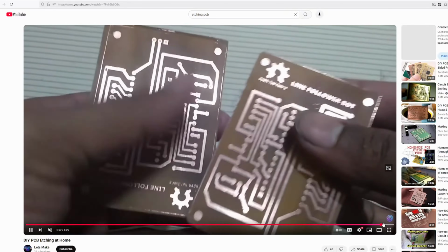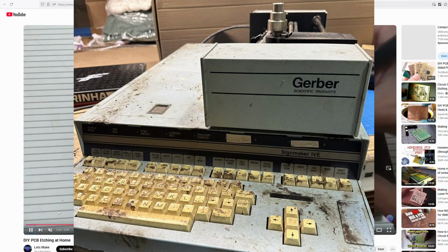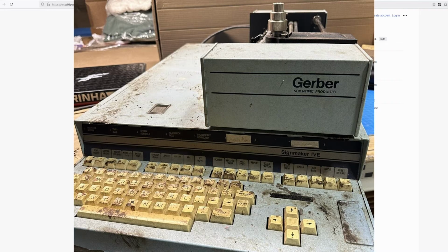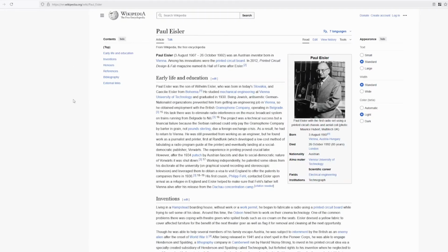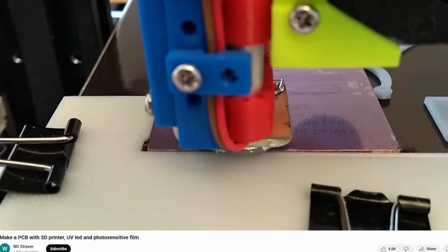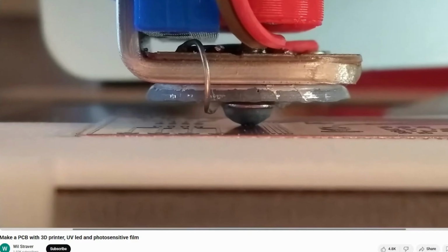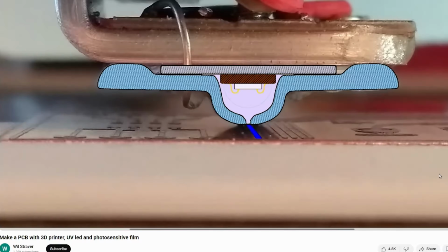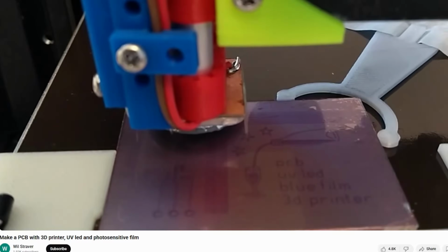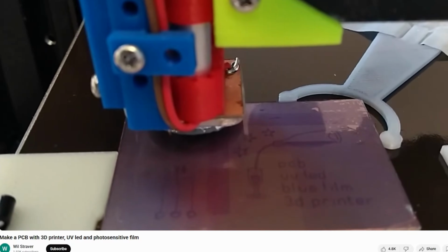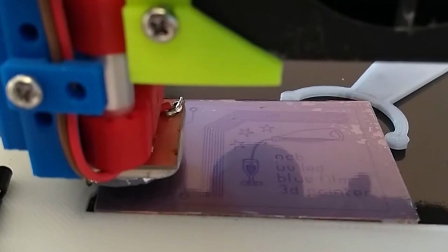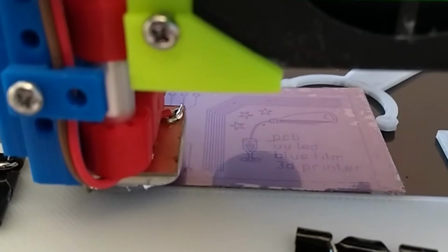If you're going to manufacture PCBs, you need a little bit of a different setup. At this point, Paul Eisler comes into the picture, and he invented a way to automate a whole bunch of this stuff with respect to the photo masking and how to do this at scale. The photo plotter is essentially a robotic light that shines light down onto some kind of photoresist, and that will essentially make the covering onto the copper layer. When you dip it into the etchant, you'll be left behind the right traces for what you needed.